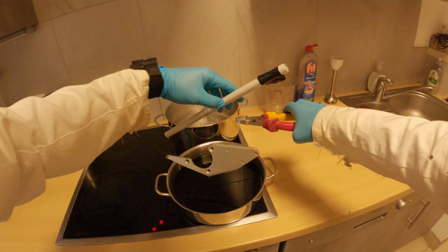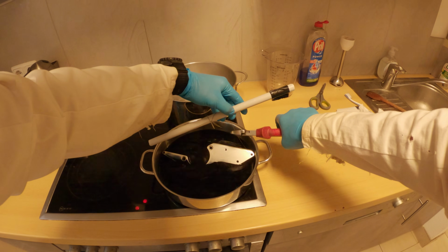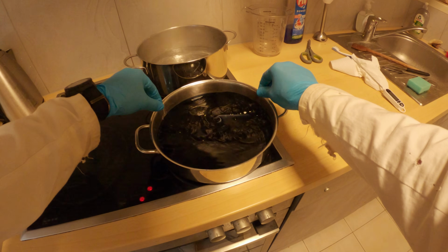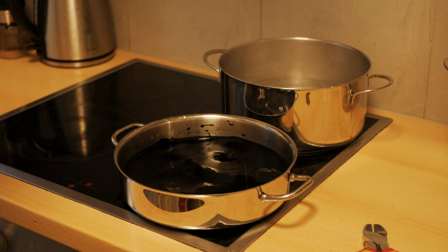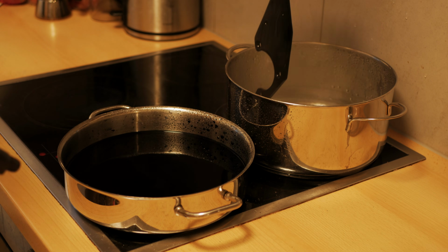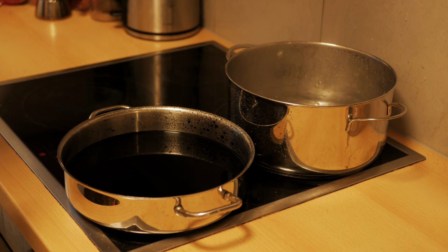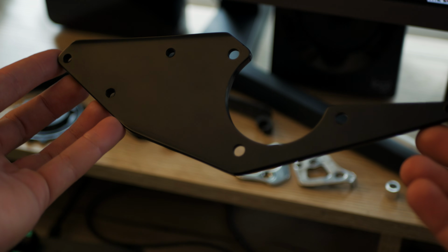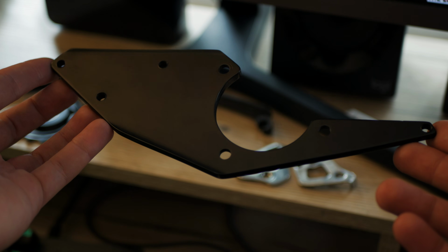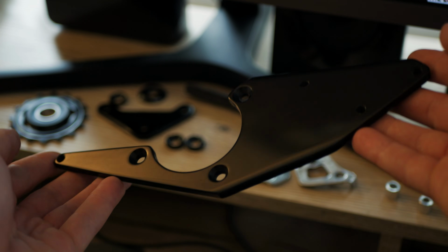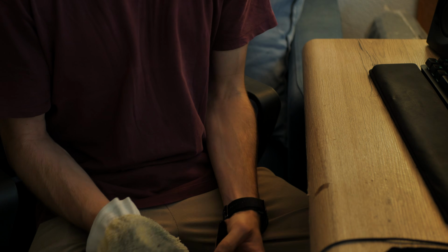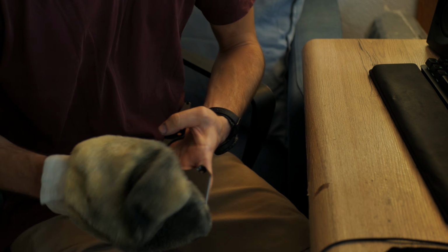I rinsed the part and dropped it into the forbidden soup. After the pores absorb the dye, I seal them by boiling the parts in water. This is what the finish looks like straight out of the sealing bath. But with about 2 minutes of polishing by hand, there was a noticeable improvement. So, I polished the rest of the plate, then continued with the remaining pieces the next day.